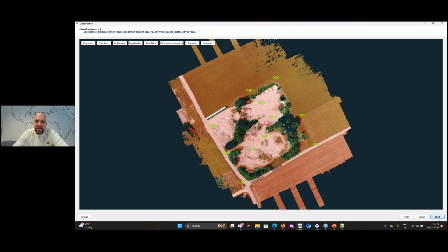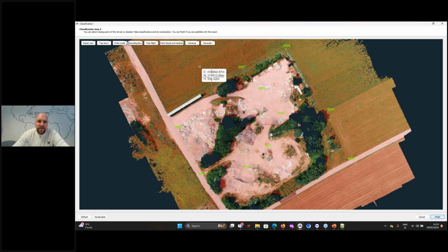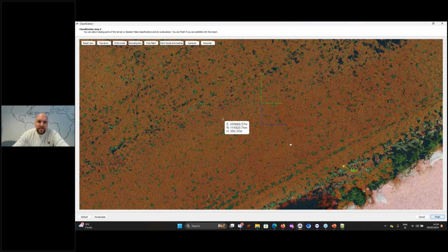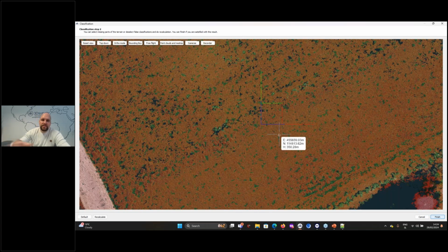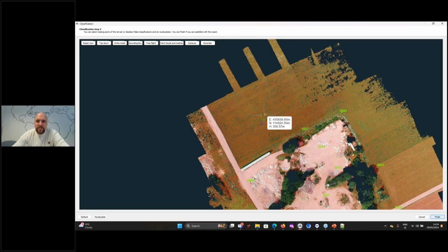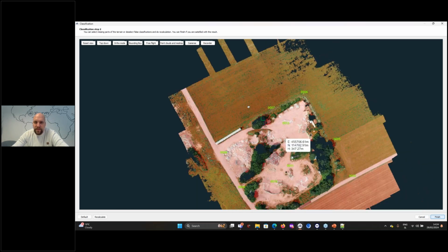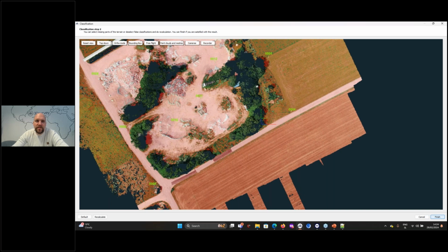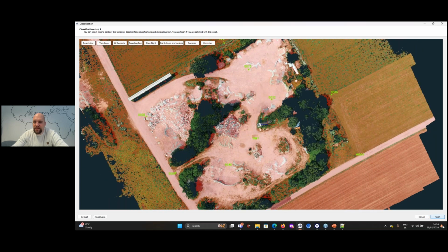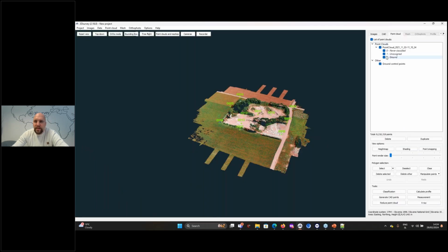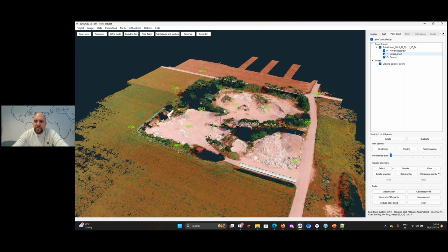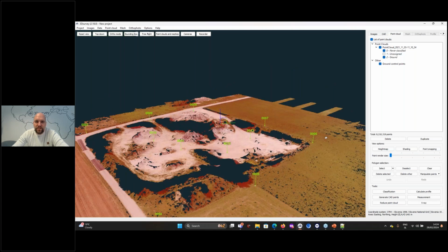And then when we click next, a second step is applied, filtering, which leaves out all the small bumps. Basically in this step, a surface is generated from the selected points, and the points that are only lower or only a little bit higher than the surface are classified as ground, and everything that is considerably higher is classified as non-terrain points. Now we'll press finish. And now our point cloud is split into ground and other points.